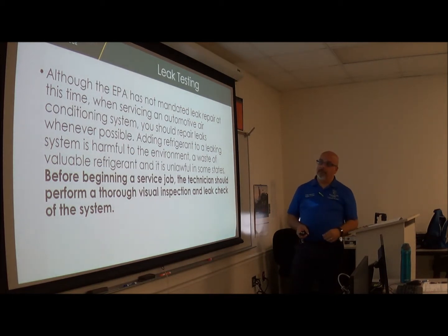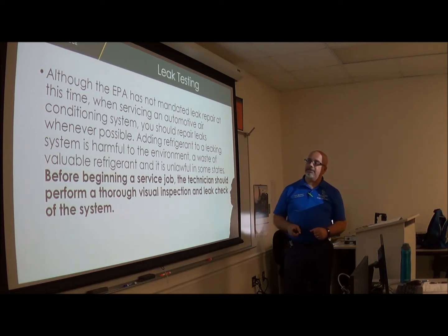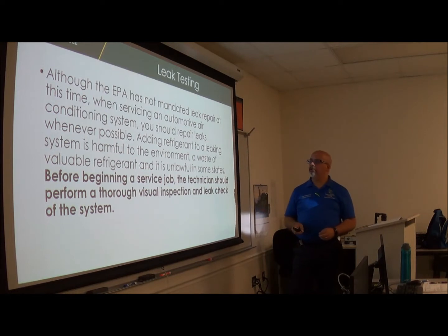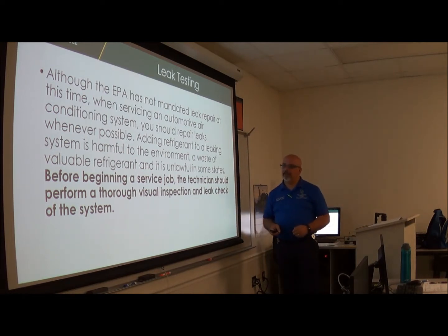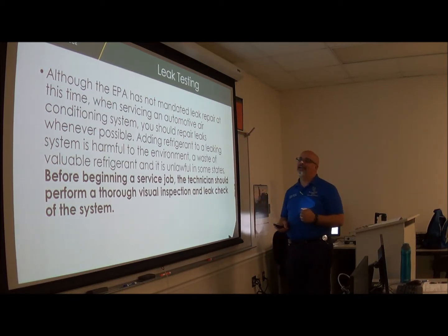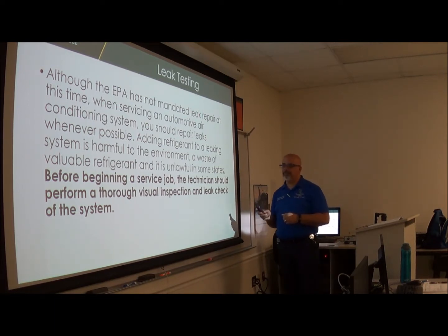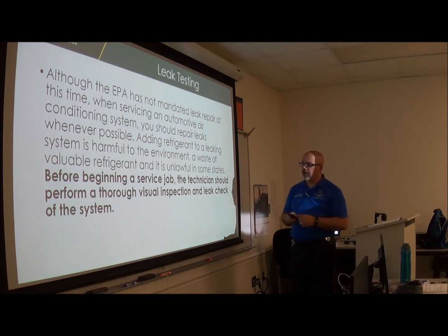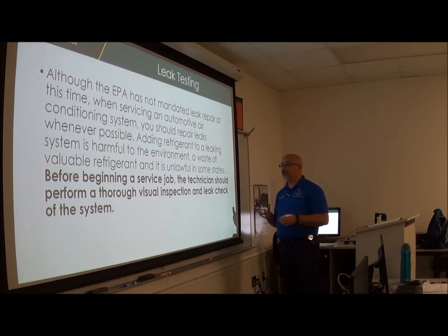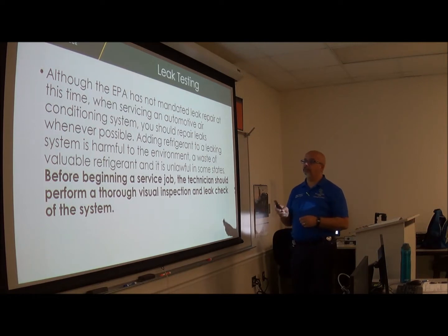Leak testing. Although the EPA has not mandated leak repair at this time, when servicing an automotive air conditioning system, you should repair leaks whenever possible. Adding refrigerant to a leaking system is harmful to the environment, a waste of valuable refrigerant, and it is unlawful in some states. Before beginning a service job, the technician should perform a thorough visual inspection and leak check of the system.